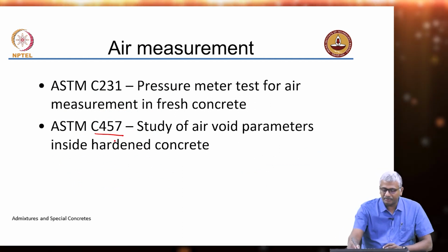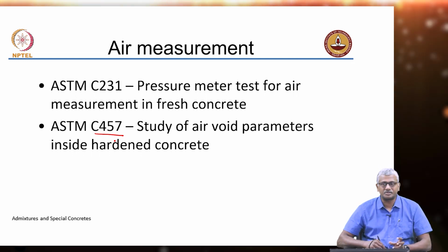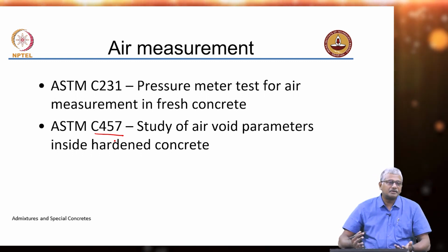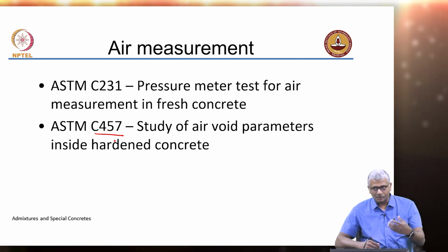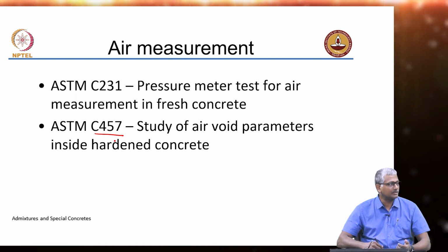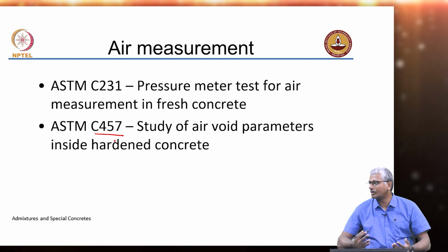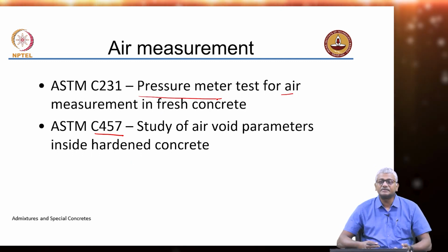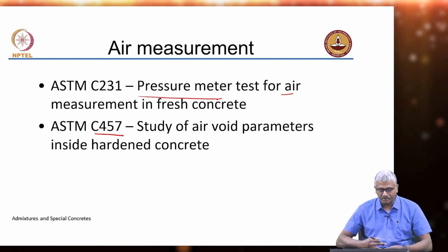The issue is heat of hydration. Amongst all cement compounds, C3A has the highest heat of hydration. So, if you were to produce a low heat cement, what would you do? Reduce the C3A and preferably also reduce C3S, because C3S also liberates a lot of heat, it reacts fast. What applications would you need low heat cement for? For mass concrete, dams, right? In such cases, you need a low heat cement. And such cements are produced typically with lower C3A and C3S contents.